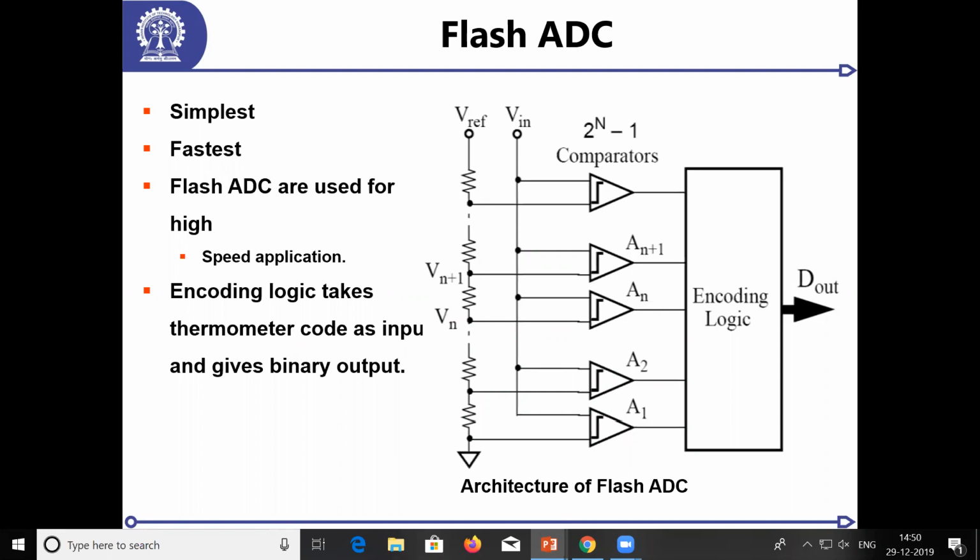Right? This is not a binary number. Binary number should be 3 bits. Now this number has to be encoded. So that's where the encoding, I said that quantization has happened. Who does the sampling? The clock that comes and triggers the comparators does the sampling in a flash. And then gives the quantized value. This quantized value is then encoded and converted back into binary.